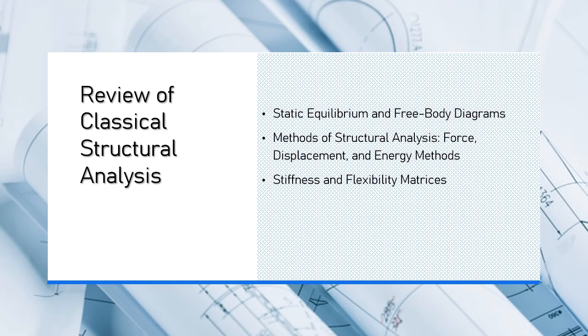In simple terms, the stiffness matrix tells you how much force is required to produce a unit displacement in a given direction. For each element, this matrix can describe how much force is needed to deform the element by a certain amount in each direction. The global stiffness matrix of a structure is the assembly of the stiffness matrices of individual elements, e.g., beams, columns, or trusses, in a global coordinate system.